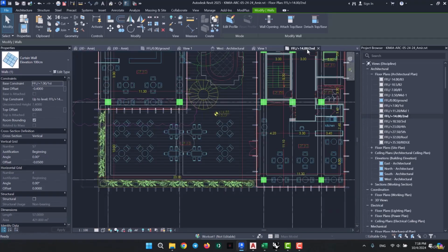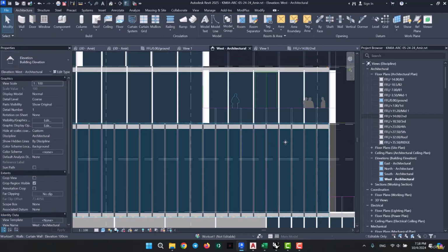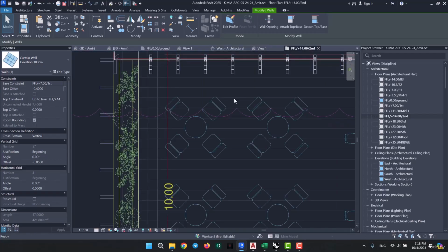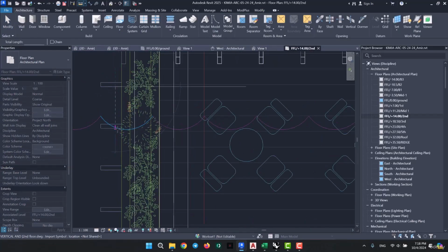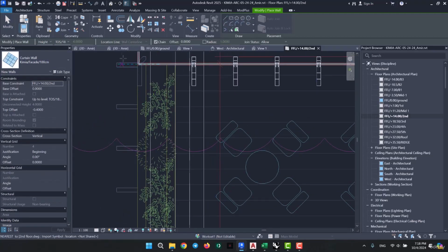First I'm going to go over here and try to measure the height, for instance, or I could just try and check the type of these curtain walls. This one right here is in fact a curtain wall that's been divided into 1 meters, so that goes for the ones on the upper floor. So I'm going to go over here and measure the distance from here to here and see that it's 1 meter. So we have 1 meter for the spacing. So I'm going to go over here and choose the 1 meter facade.